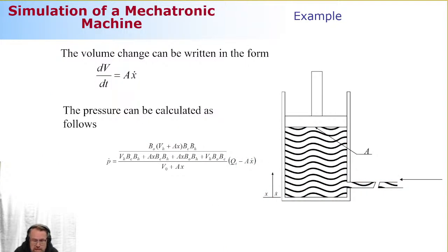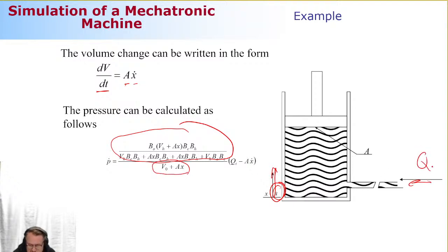The change of the volume is the cross-section area multiplied by the piston velocity, so it's x and x dot. Again, I have my positive assumptions as shown in the figure. The final thing I need to do is the substitution. This is the effective bulk modulus, and this is what I get when I compare with the total volume size. The flow rate in was substituted here, positive in sign. The one taking away flow rate is the piston traveling in this direction with a certain positive velocity.